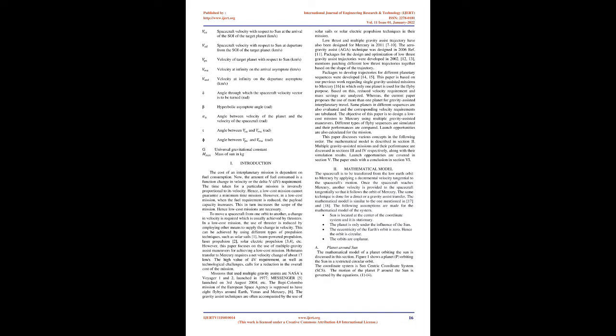Velocity at infinity on the arrival asymptote, km/s. Velocity at infinity on the departure asymptote, km/s. Δ: angle through which the spacecraft velocity vector is to be turned, rad. Hyperbolic asymptote angle, rad. Angle between velocity of the planet and the velocity of the spacecraft, rad.